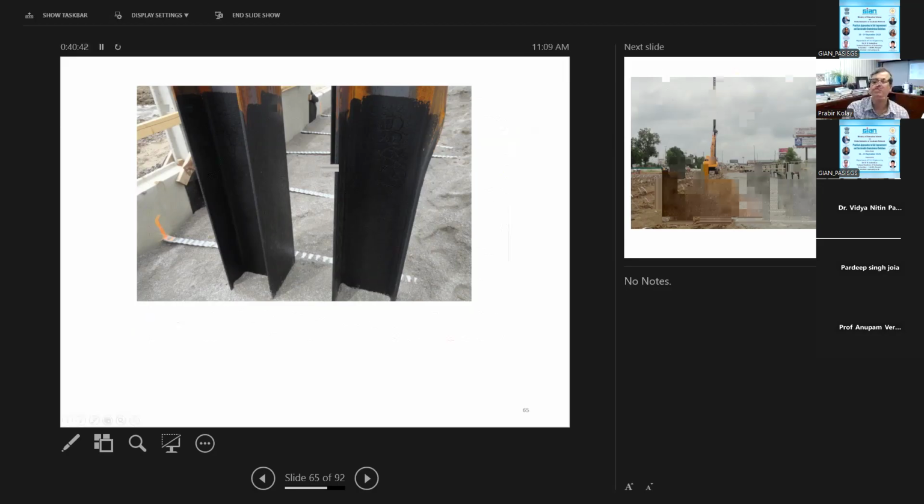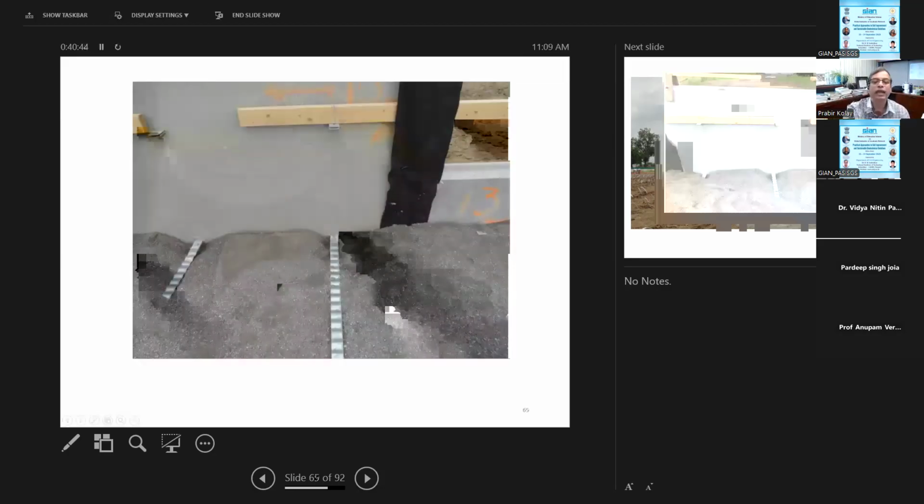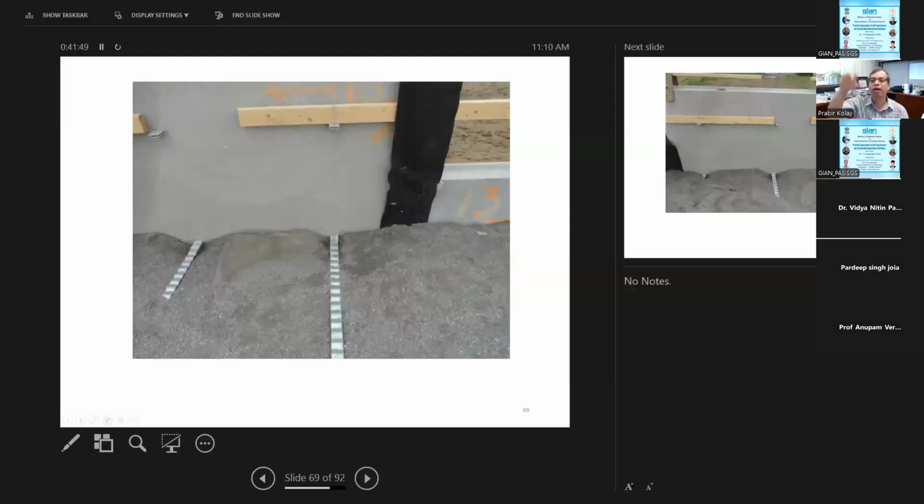How it looks like, there are holes that can be attached. So you can see here, this is the reinforcement strip, and this is the gravel type of material they used. And this is the horizontal spacing over here, from here to here. And this is the next one. After this, they will fill it with the granular soil. And then the next one will be attached on this groove over here. So this will come horizontally. So that will be the vertical spacing. And this one, you can see the horizontal spacing. This is how they do it with this MSE wall.